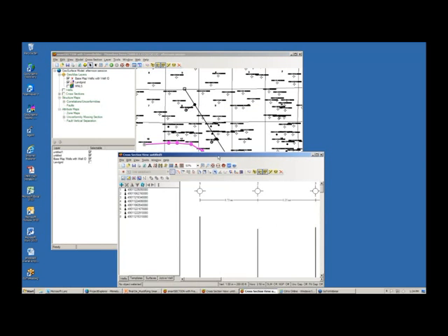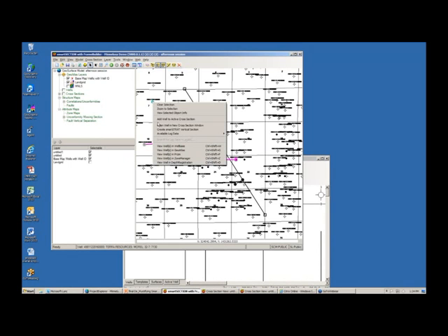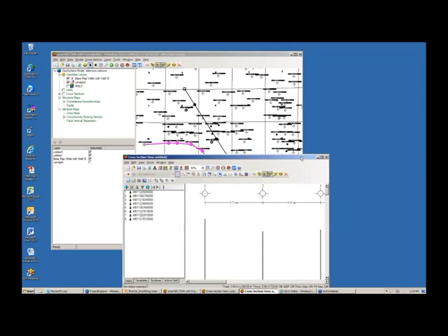Now, one other comment I'd like to make is when you are clicking on your map, you can just select a well, do a right mouse button, and you can actually also see the available log data listed here in this little drop-down box. So it's very easy. Or you could choose your favorite Geo Atlas map that happens to have where all the rasters are, where all the good vector wells data are, etc. So you can easily use those layers as well.